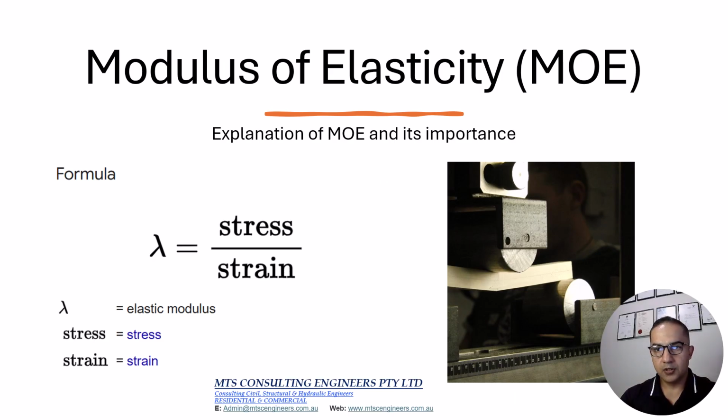To know how much a piece of wood will deform under stress, or how to predict the stiffness and deflection of timber beams, we need to measure its modulus of elasticity. In the simplest terms, the modulus of elasticity measures a wood's stiffness and is a good overall indicator of its strength. Technically, it's a measurement of the ratio of stress placed upon a wood compared to the strain, or deformation, that the wood exhibits along its length. It is a crucial factor in understanding timber performance. It measures the stiffness of timber, which is essential for ensuring structural stability.